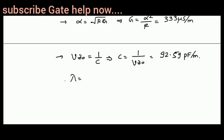Also lambda is required. So lambda is V by f, velocity by frequency. V and f are known to me. So this is 1.8 meter. In this way you can solve the problems of distortionless transmission line and the lossless line.